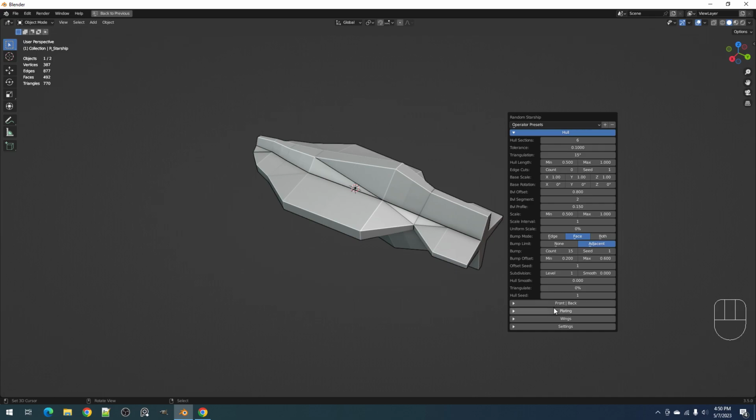And then smoothing in the front and back 1. You can also use just 0.5 if you want. This is just to make the plating and bump affect these areas better because of the different elevations created by the smoothing.